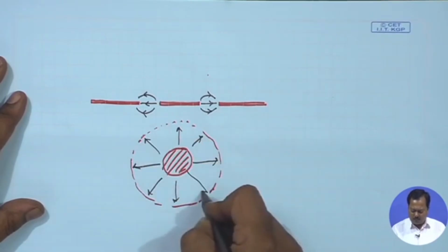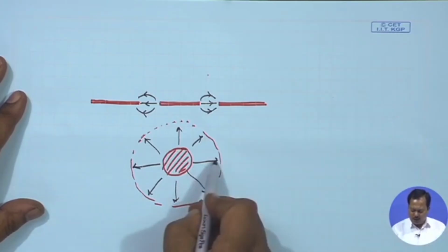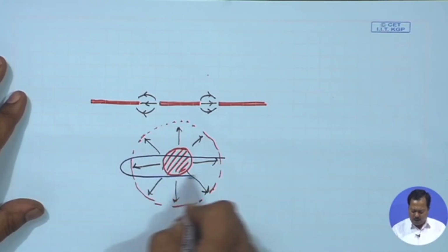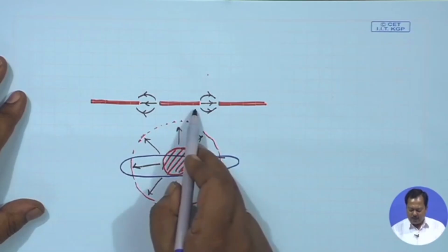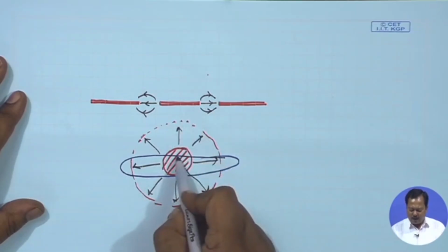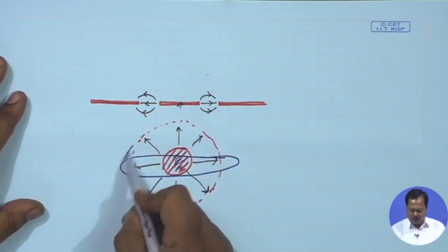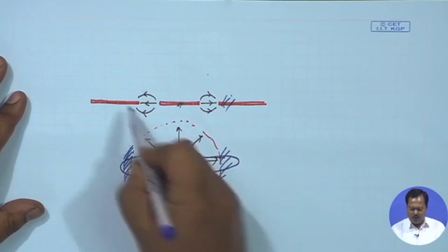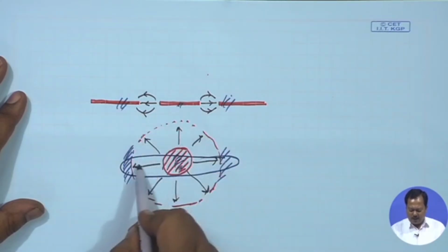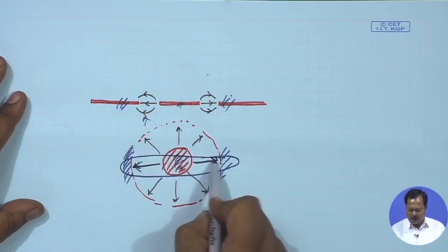So, you see, then simply we can use this part of the coaxial cable. We can connect this part of the coaxial cable directly to the CPW line. We will be soldering the central conductor to the signal line and this outer conductor, this part, to the ground plane, and then this component of the electric field will excite this component, and this right hand side component